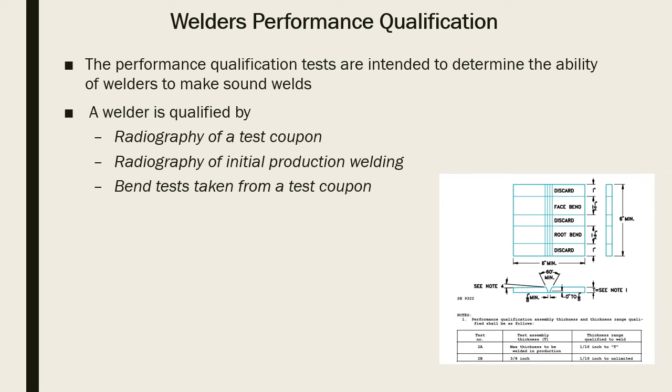Here's kind of a little variant: they're going to cut a face bend and a root bend out of this thin material, slice it, and call it good. You're going to look at the bend test samples, and if they're good, the guy passes. If not, he didn't pass the weld test.